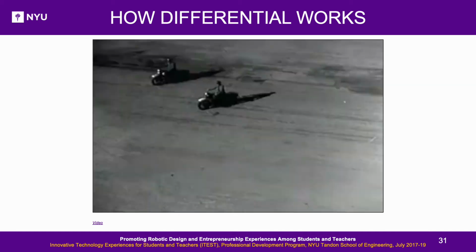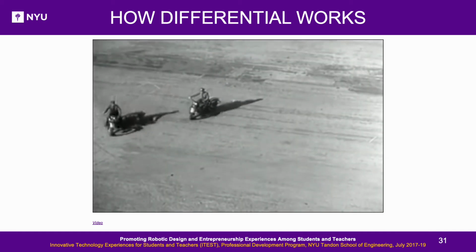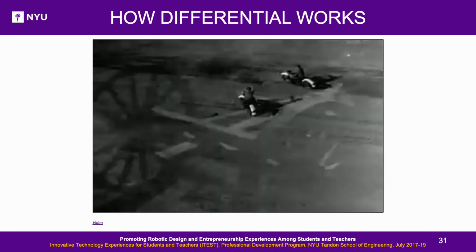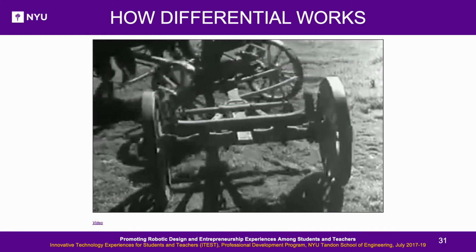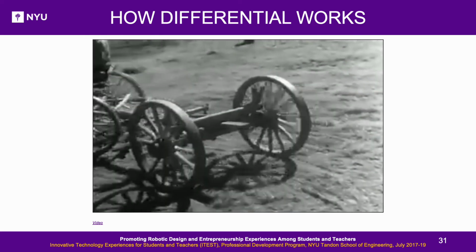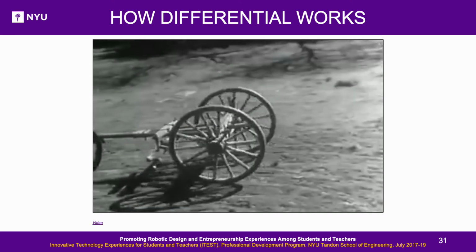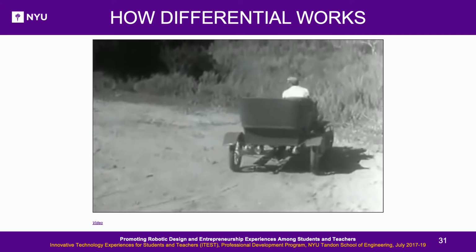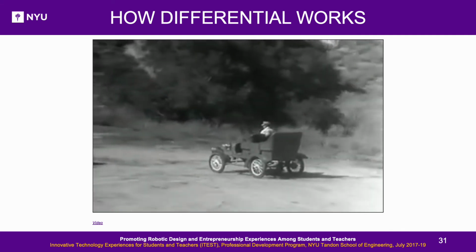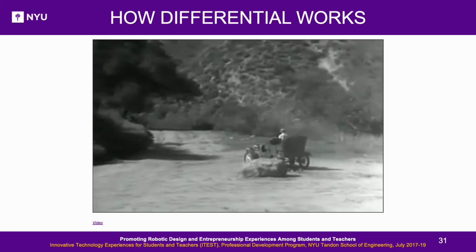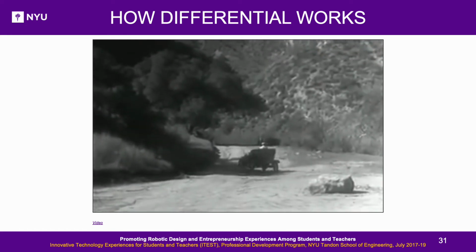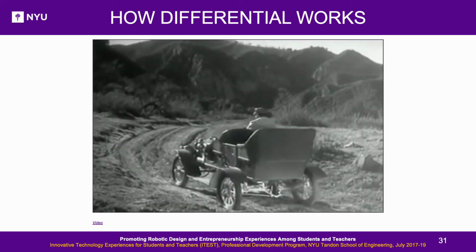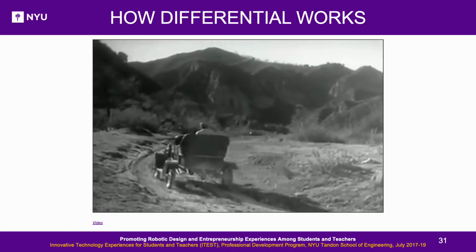The outside wheels must spin faster than the wheels on the inside, because they have a greater distance to travel in the same length of time. When a wagon turns a corner, the wheels can travel at different speeds because each one can turn freely on the axles. And in the early automobiles, the rear wheels turned separately and only one wheel was connected to the engine. But when only one wheel was driven by the engine, it had to do all the work, and it couldn't get a good enough grip on the road to do its job properly. So the one-wheel drive was soon out of date.